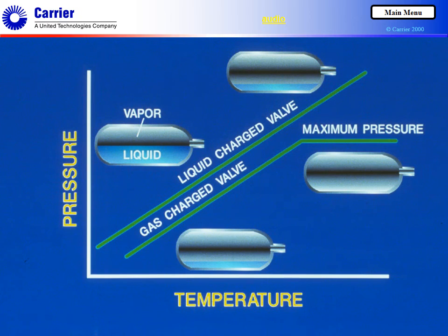In the valves shown so far, there has been sufficient refrigerant vapor in the sensing bulb, its tubing, and the area in the valve above the diaphragm that there always is some liquid refrigerant present in the bulb. For this reason, the term liquid charged valve is sometimes used. The limited charge valve, on the other hand, is an MOP valve that has enough refrigerant liquid present below the pre-selected maximum operating pressure and temperature that goes with it.